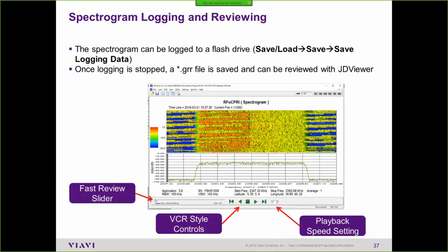The other thing you can do, if, say, you're interference hunting, driving along the road looking for an interferer, is turn on this time cursor. It'll stop the measurement, and you can then move this position indicator that's right here, that little green arrow. You can move it back in time to capture the signal when it popped up. And again, that screen is most useful for interference hunting.